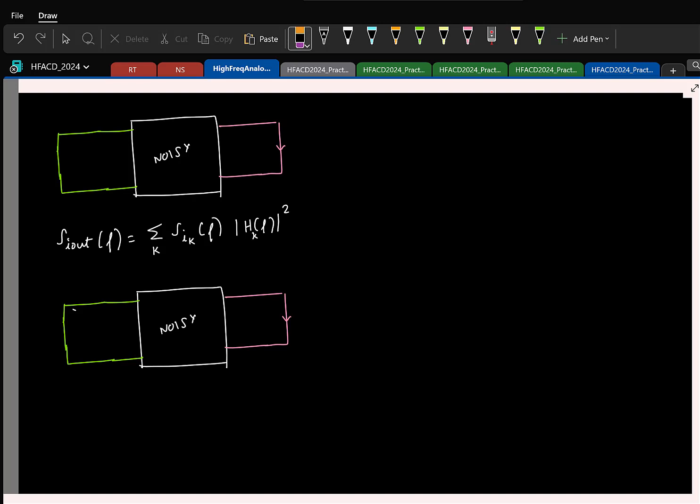So what we did was take the same network and say that the network is noiseless, and the noise is coming due to an equivalent voltage source, Vn,in. But this is nice only as long as you don't have any source resistance. As you know, the input exciting the network will have a source resistance, which is not under your control and is not known beforehand. So if you have a source resistance here, in the model also you'll have the same.